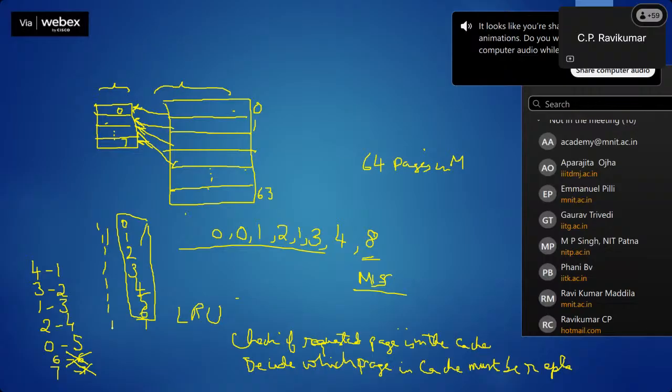So I want you to think about a cache controller. Keep the memory simple, only 64 pages. Because you are using 64 pages, assume that each page has maybe 1024 locations. So the whole system is 64K. There are 64 pages, each of 1K. So the memory is only 64K, and the cache is only 8K.